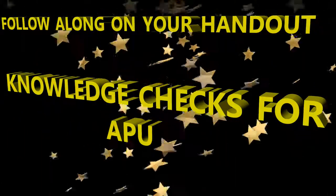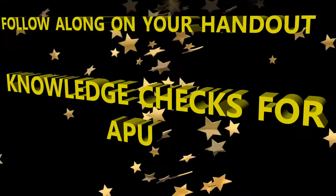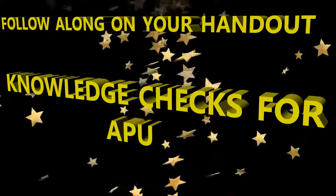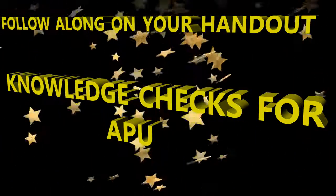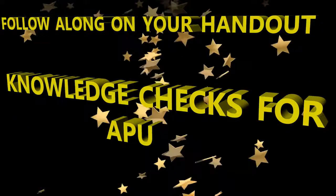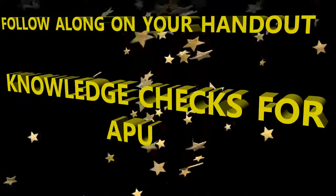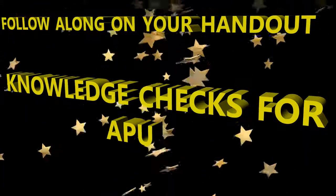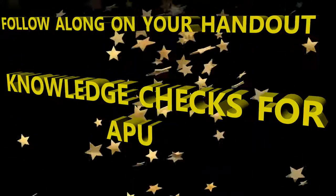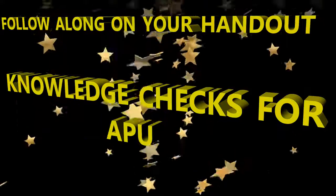And then you also have your start sequence, normal shutdown, explaining the different APU percent of speed at which things start to shut off, like for example your starter motor at 50%, and things start to open or close. So basically that's giving you the gears that are going, figuratively speaking, when you hit the APU master switch to the on position.